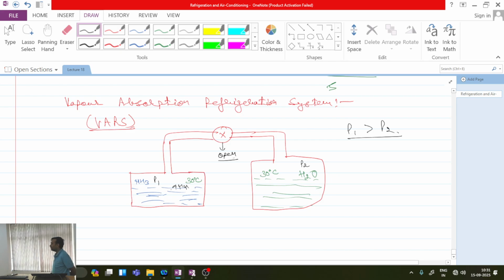Is this point clear? All are clear with this point or not? So in the remaining portion, because more and more ammonia vapor is forming, whatever ammonia vapor is forming is taking the latent heat of vaporization from the remaining liquid. So this is called the evaporation process, and we always know that evaporation causes cooling because it takes the latent heat of vaporization. So that's why its temperature will start decreasing. But if its temperature decreases and this vapor just keeps on depositing over here, then after some time this pressure will become the same and the process will stop.